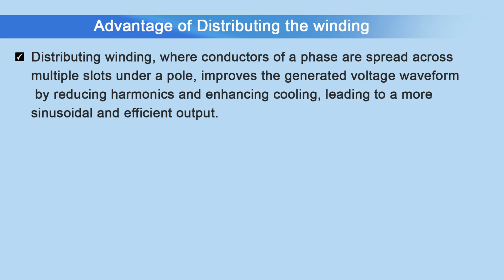Apart from that, in vehicles we are using an alternator to charge the battery. It is easier to convert this AC power to DC with the help of a rectifier instead of using a DC generator at that place.